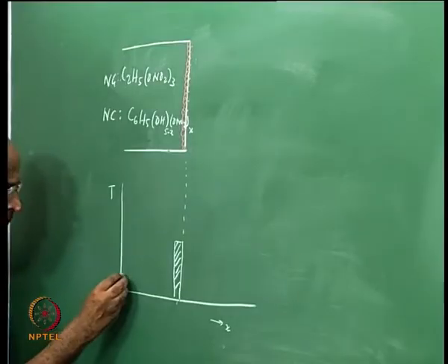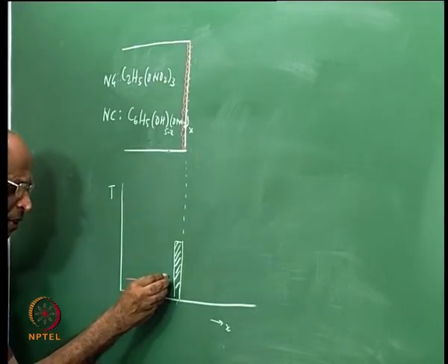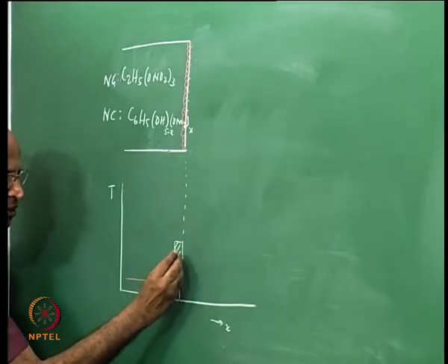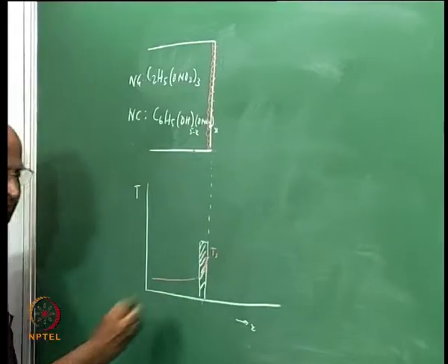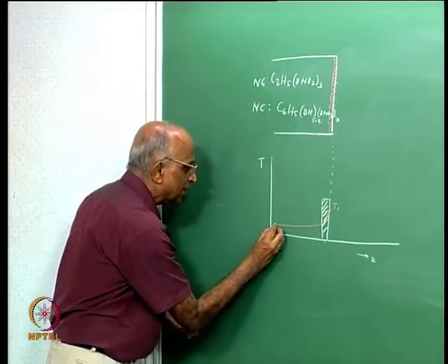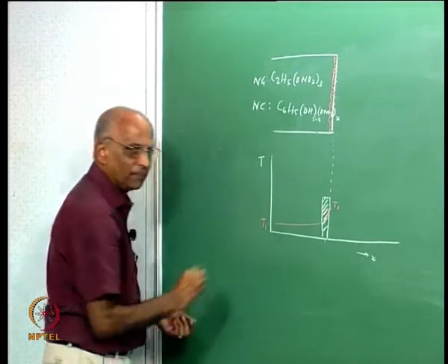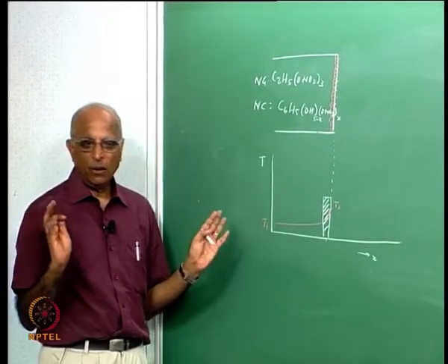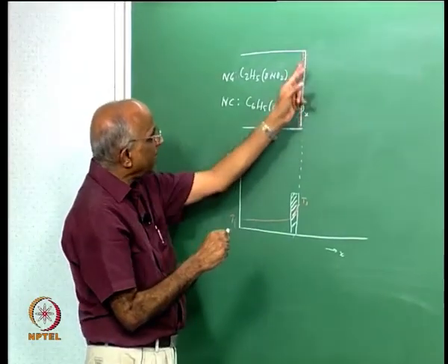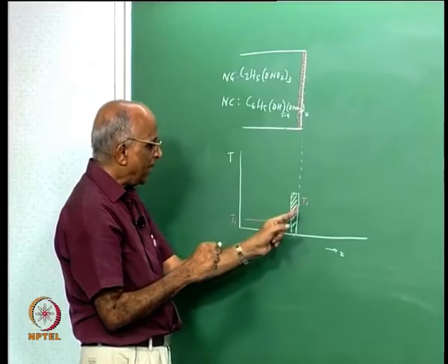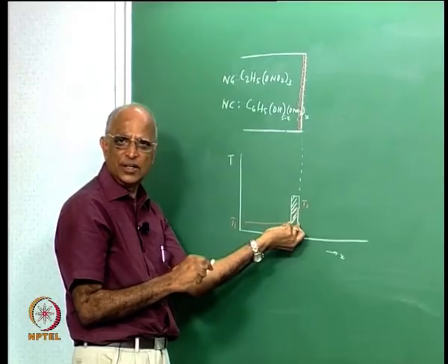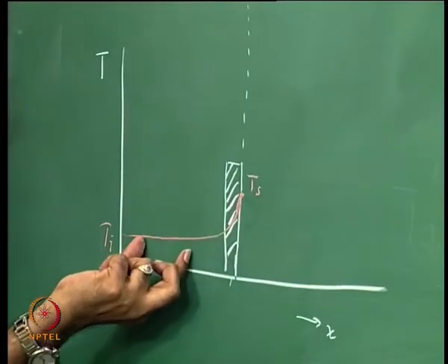Let me show it in red. The depth is really not heated, maybe it begins to get heated, the temperature rises, and here I have the surface at the temperature Ts, and this is the original temperature, let us say the initial temperature of the propellant, Ti. Okay. All what I have done, just like I ignited with a matchstick the sparkler, I ignite this particular surface, and therefore the surface temperature increases, heat gets conducted over a certain thickness, and thereafter the temperature is the original.